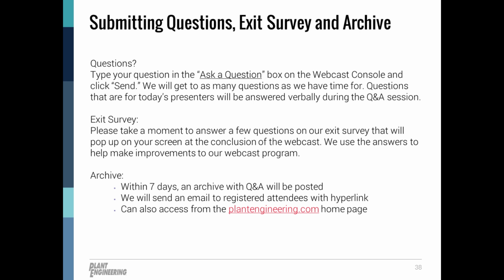Thank you, Ronnie. Michael, let me ask you a question. When is it all right to overload a motor? Yeah, so it really depends. We did talk about the service factor. In an induction motor, you're going to be able to get a high amount of torque out of these things for short periods of time. And so we showed the curves, the NEMA design curves. You've got the breakdown, basically. Breakdown, we're talking about 250% rating sometimes.